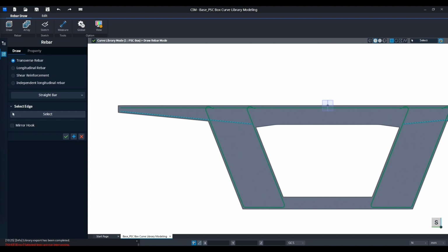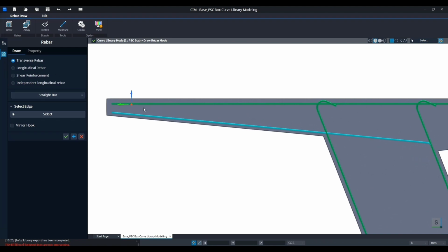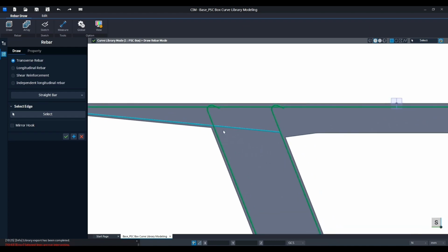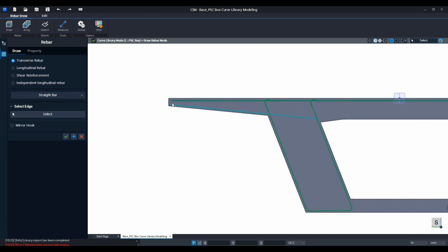So it's time to draw. We would like to draw the member, but in this case we would like to use the select line. Why do we want to use the select line? Because the area that we want to cover is only this part, so we don't need to have a lot of maneuver like in this part and this part, because in this rebar we will have to cross this different shape, and also in this part we have to cross different shape and different space.